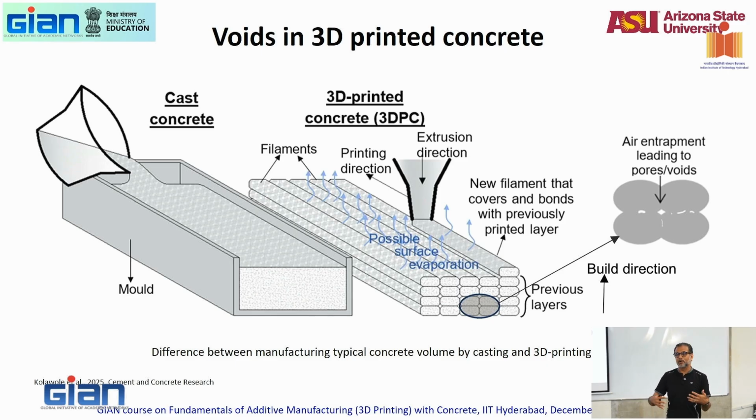That's what it is. Even if you do all the regular stuff, you will get good concrete. So if you say that I designed for 30 megapascal and then a year later somebody drills a core out of it and gets 10 megapascal strength in concrete, somebody has worked really hard to not put the cement and not cure and do all of that, right? So what we end up with is a good quality finish, good quality material generally.